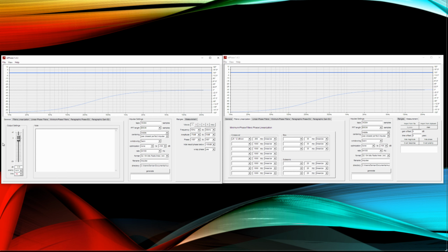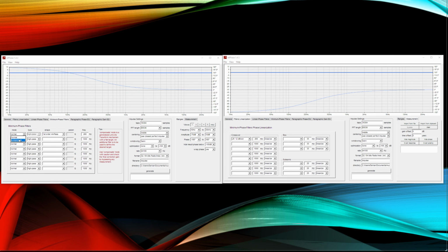Okay. And another way to time reverse the filter is using this compensation here. This is also compensate mode, is time reversed. So you can selectively time reverse some of the filters and don't reverse some of them if you really need to for some exotic corrections. Anyway, now let's go and check for the other one, the 2700 filter. This is its shape, minimum phase again. Let's make it normal and let's choose second order all pass and 2700.